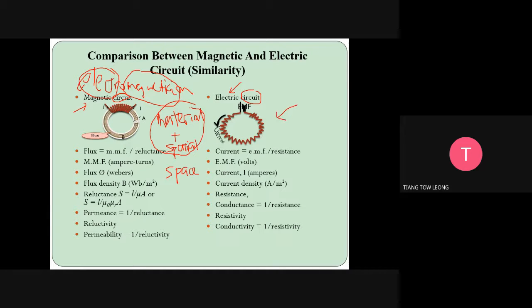In the electric circuit we are not seeing the 2D or 3D geometry; we don't deal with that. But here we need to know the geometry. What is the length? Is it circular, solid, or rectangular? So that we know where the flux flows through the area, and what the material inside is. One is spatial, like the area; one is the material, the mu. This is the difference, but we want to make it simple. That's why we have a magnetic circuit.